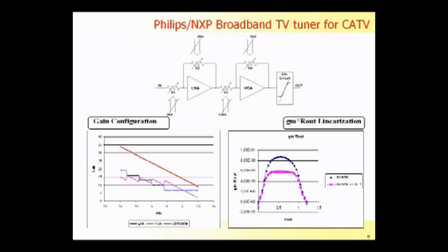So we can see plotted the product between gm and R out without the linearization circuit of an inverter, and we can see that it is not flat, so it is not so linear, and with the linearization circuit it is now really flat. The drawback is that we lose a bit of gain, but this is an open loop simulation. So when we close the circuit in feedback, this drop is not so evident, and the gain is almost the same.